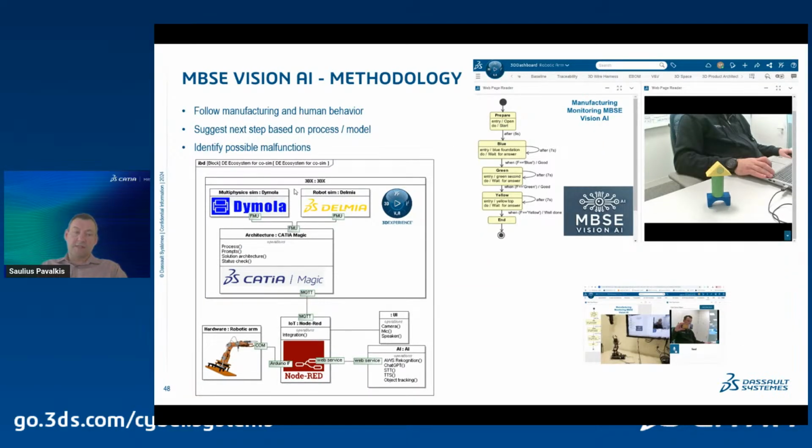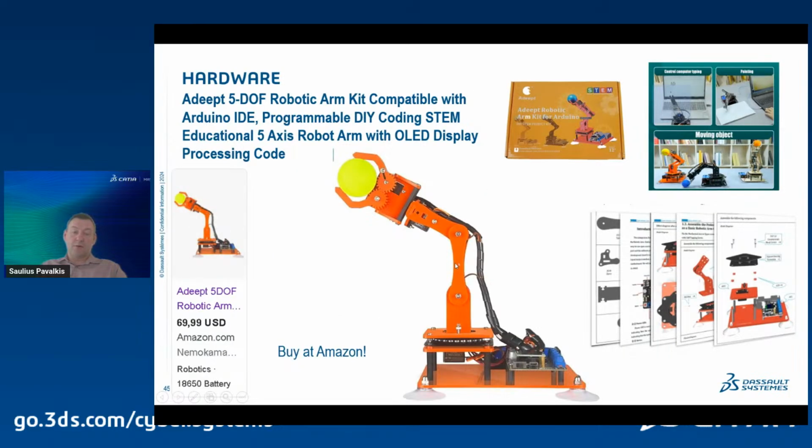Talking about interesting use cases. For example, because this robotic arm has servo motors, they don't provide position. They are listening for position. So we are sending from CATIA Magic, from 0 to 180, a position for each servo motor, deliberately very straightforward communication and control, but they don't give you the actual position where they are. So we thought, okay, we need some sensors, and definitely with sensors you can achieve many things. So we thought, okay, what's the best sensor?